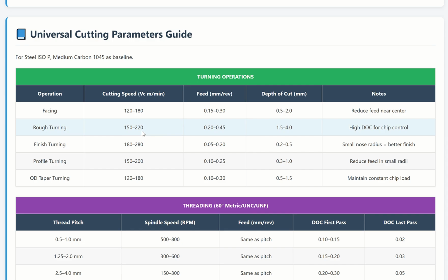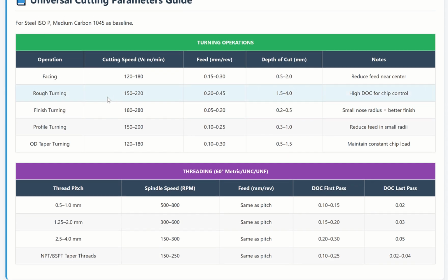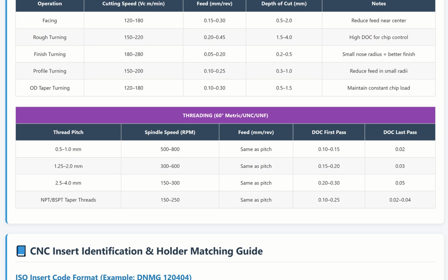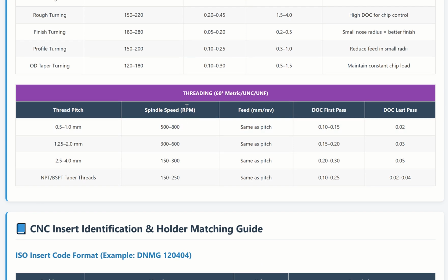Each one of these materials will be very good for you when you're programming, because at the end of the day, you need to give a client quality work. So understand the cutting parameters, and understand the right tool for threading, either ISO, or UNC or UNF or NPT. This is very important.